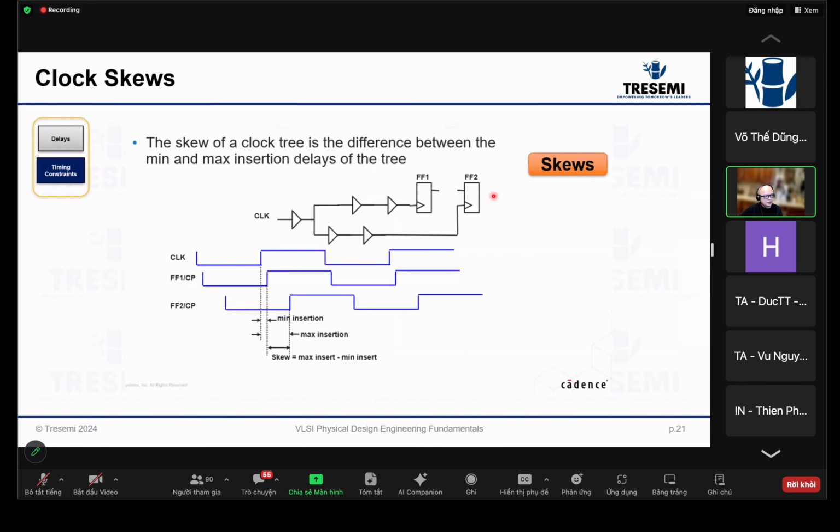And on clocks, you deal with clock skew, meaning in real life, all the delays through all these gates vary depending on your circuit, because of physics. The temperature, the process variation, everything guarantees that you have different arrival times, even though you have one source clock and the same number of buffers going to 2 different clocks. You're still going to have a variation in arrival time. So the difference between the minimum arrival time and the maximum arrival time is called skew.